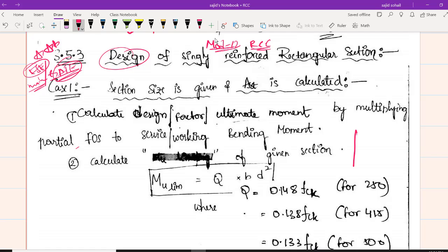Whenever I am talking about beam dimensions, length, this is your length. Okay, आपको लेंथ नहीं दिखाई देगा. When I am talking about cross section, all you can see is breadth and depth. Depth is represented by capital D. याद रखना, depth is represented by what? Capital D. And there is also one more term which is called effective depth, which is from top to centroid of your steel. इसे हम क्या कहते हैं? effective depth कहते हैं. Effective depth. And what is this difference? This difference will be your capital D minus small d,